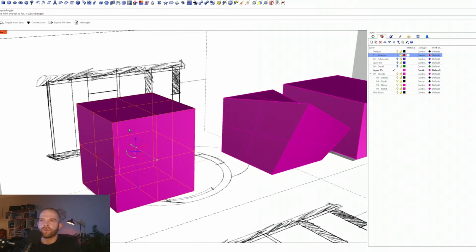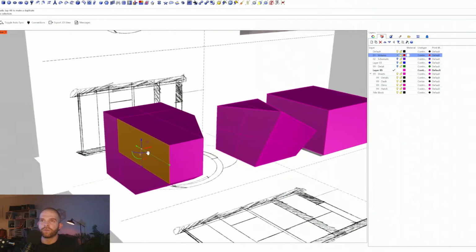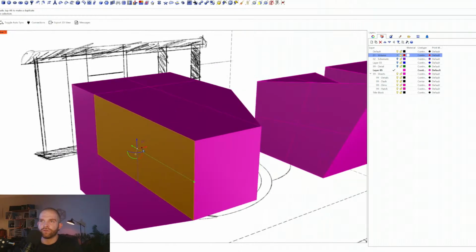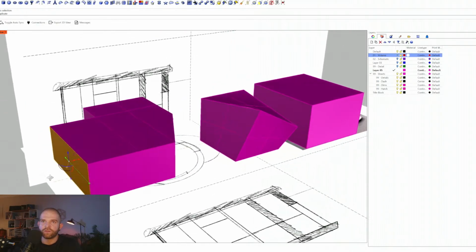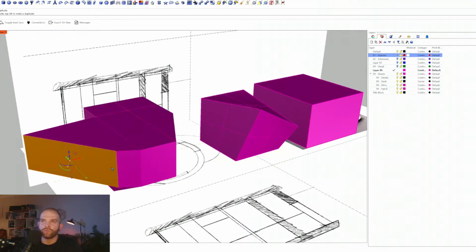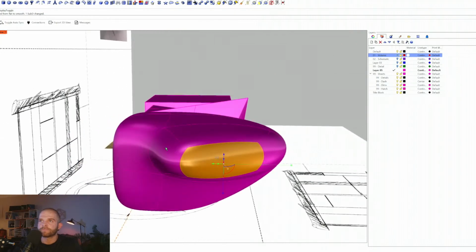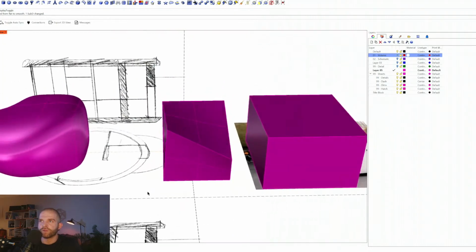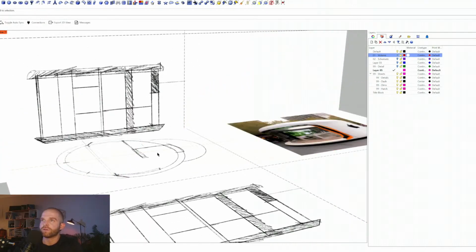So if I were to modify it from this, I can kind of tell what I'm doing with the bones. Like say I move it out this way. And also with meshes, you get this little dot on the arrow right here, which means you can extrude. So that creates another set of faces to continue building on. But here I can twist this. And then if I hit tab, right, it still sort of curves on that SubD geometry. So anyway, that's how you want to use that.